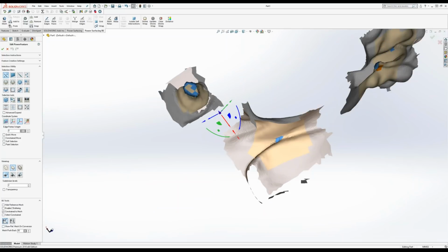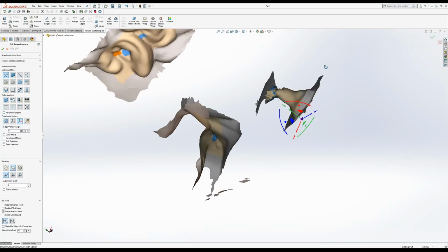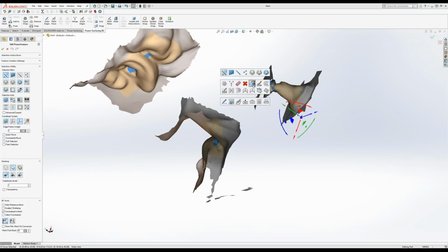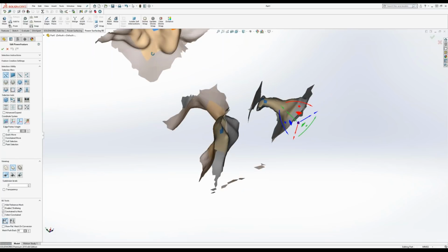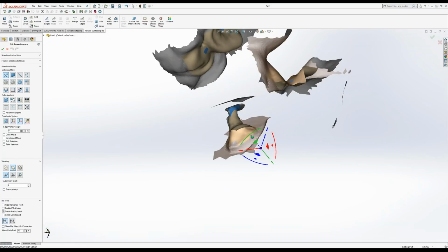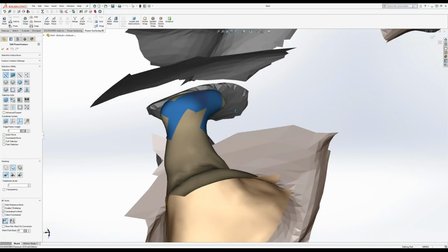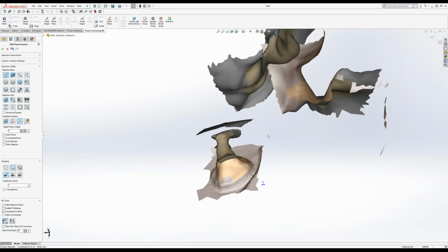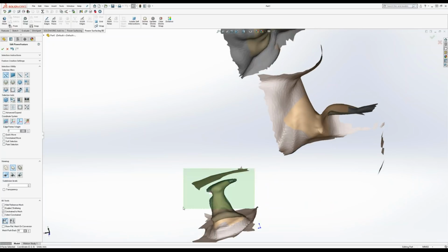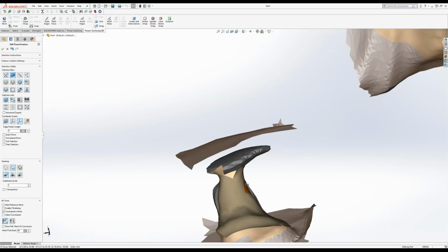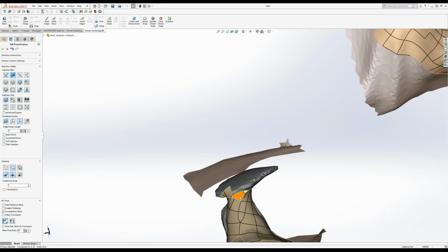There's a small area here where there's some self-intersections, and here. Now we can handle most of these self-intersections simply by removing the constraints on them, and that will smoothen them up. You can see what happened there to those guys. As a matter of fact, it probably has made this one good enough. I could, if I wanted, and let me do this anyways, just to show you how you might do that, let me grab some faces here. We could say, I really don't want that mess in there. That pocket really wasn't supposed to be there. So I can delete these guys and then go ahead and fill them in.